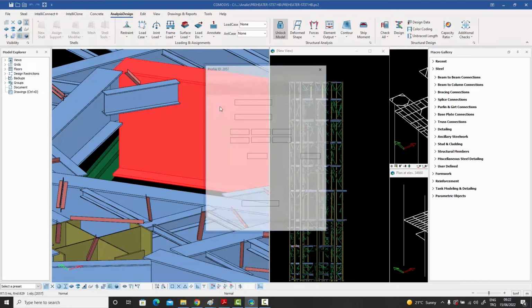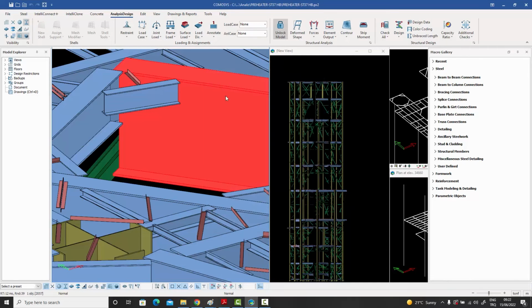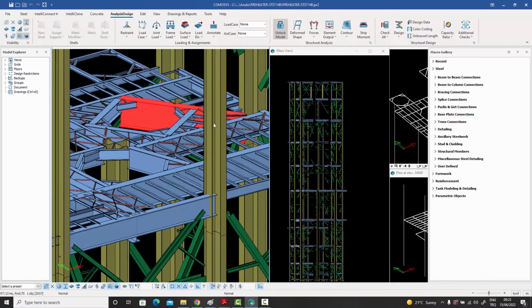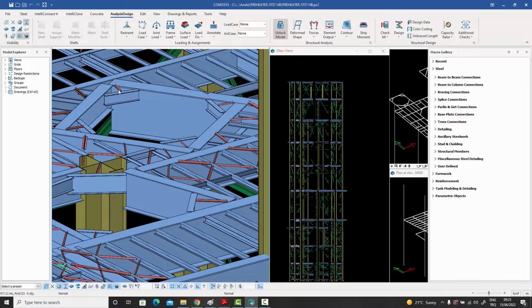But a beam as big as this, which is say a 2-meter high beam, the moment is going to dominate as far as the section design is concerned. Or some deflection criteria might be dominating. It depends on the span and all. But unless it's a very, very short beam where the shear dominates, more often than not, perhaps more than 90% of the cases, more than 95% of the cases, you will have reasonably small shear loads at the ends.